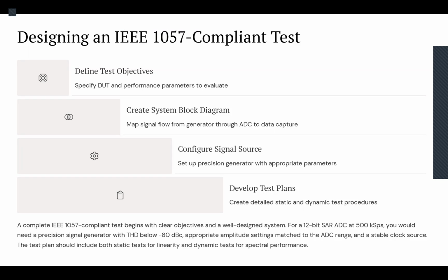On the other hand, all the test instruments must be calibrated, so we know that they are accurate, and we have the uncertainty of each step and each range of the measurement for each instrument in hand. So we could analyze and identify the errors introduced by the testing instrument that we use. We could separate the actual errors in the ADC from the errors that we introduce into the test.